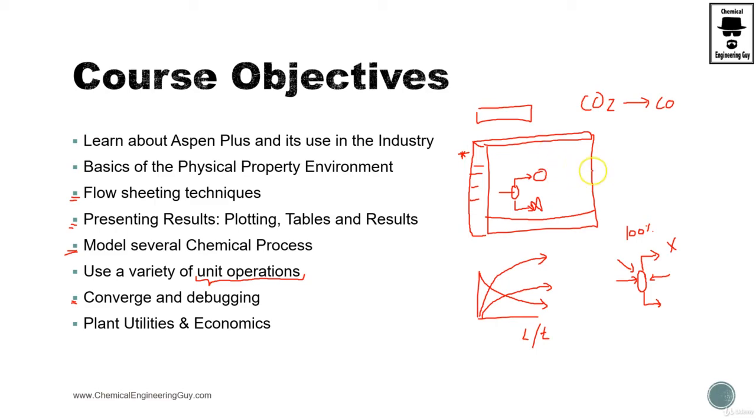Those are easy to get also when you are setting up columns or flashes. The important part is to understand what's happening and fix it. Typically you get a report on how Aspen is running all the processes and equations, but sometimes it's really hard to understand what the error is. Here is where we're going to check how to converge and how to debug. Sometimes you're going to have warnings, which are shown in yellow. Even though they are not that strong, they must be attacked. You must understand what's happening.